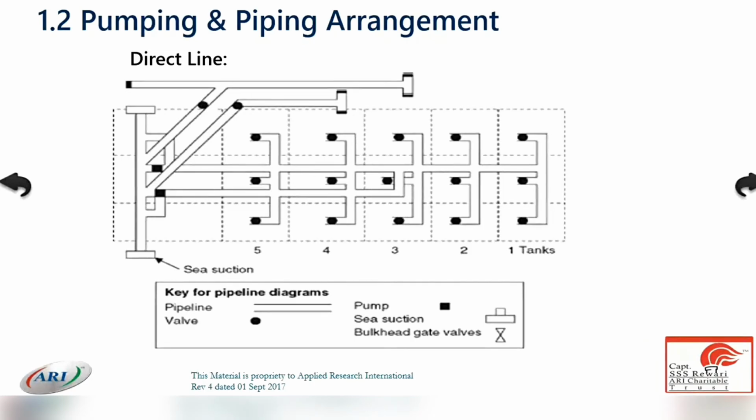Vessel designed mainly to carry one grade of cargo only. Not very versatile. You cannot do much. There's only one way to discharge, not too many options available. If there's a problem on the gate valve, it gets difficult for discharging as well as loading. Suppose the gate valve is not opening or the spindle which is coming all the way to the deck breaks. Less maintenance as there are very few pipelines or valves involved in the system, and relaxed discharging, relaxed operation. Mainly used on a storage tanker or very large crude carrier.